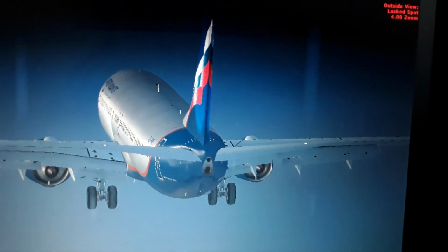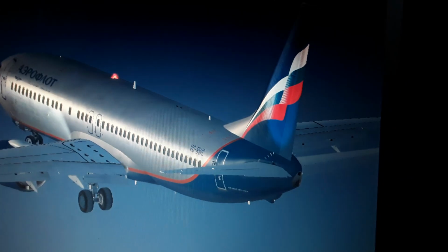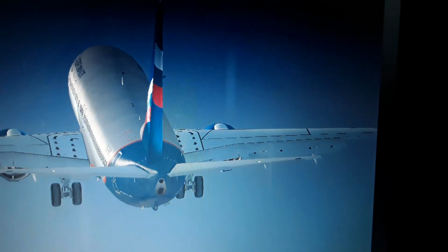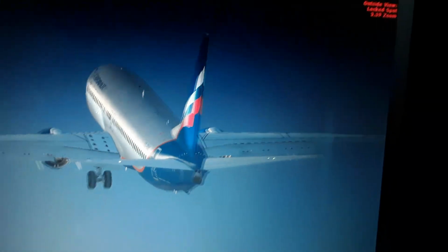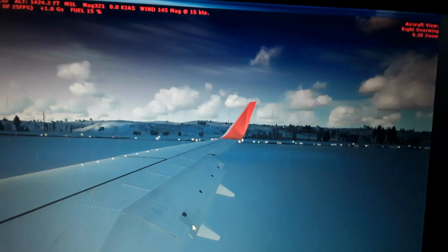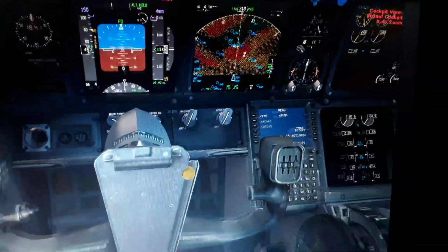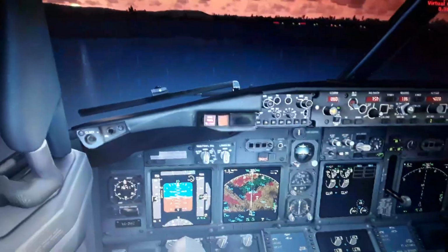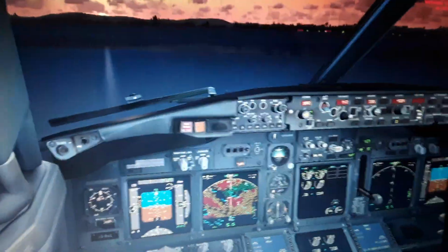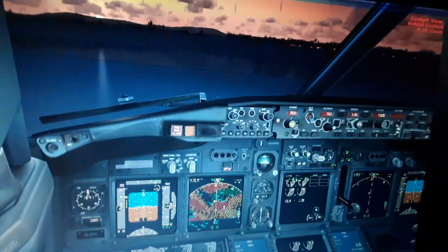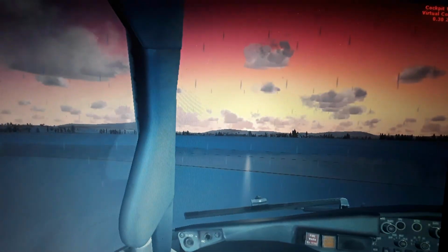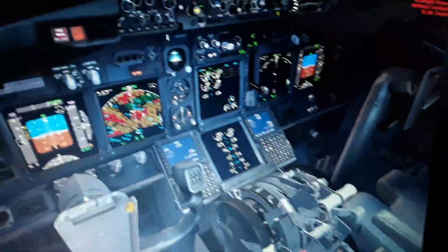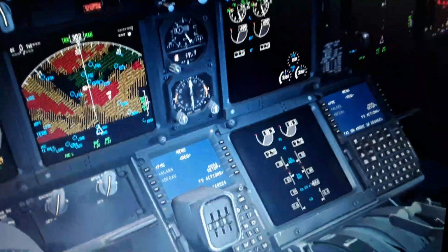And here we have the elevator, the horizontal stabilizer elevator, which is in the tail section, and the rudder, which we control with the rudder pedals. And we use all these control surfaces in the wings for modifying the dynamic pressure in the wing. So we change differential lift between the left and the right wing. That causes the aircraft to roll, or pitch up or pitch down, for climb or descend while flying. So I will be showing you a little bit more things right now.